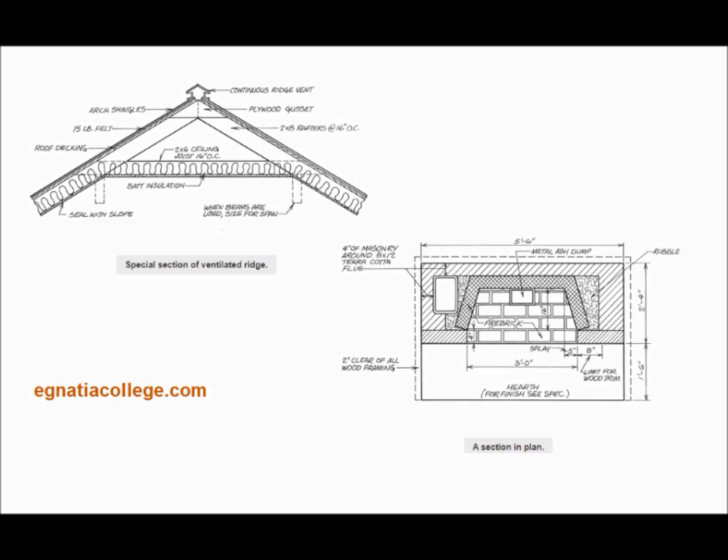Sizes of floor framing materials. Sizes of wall framing materials. Wall covering, sheathing, siding, stucco, masonry, and interior wall finish and insulation. Cornice construction materials and sizes. The cornice is the construction at the roof eaves. Ceiling construction and insulation. Section views are used to show any special construction that cannot be shown on normal plans and elevations.